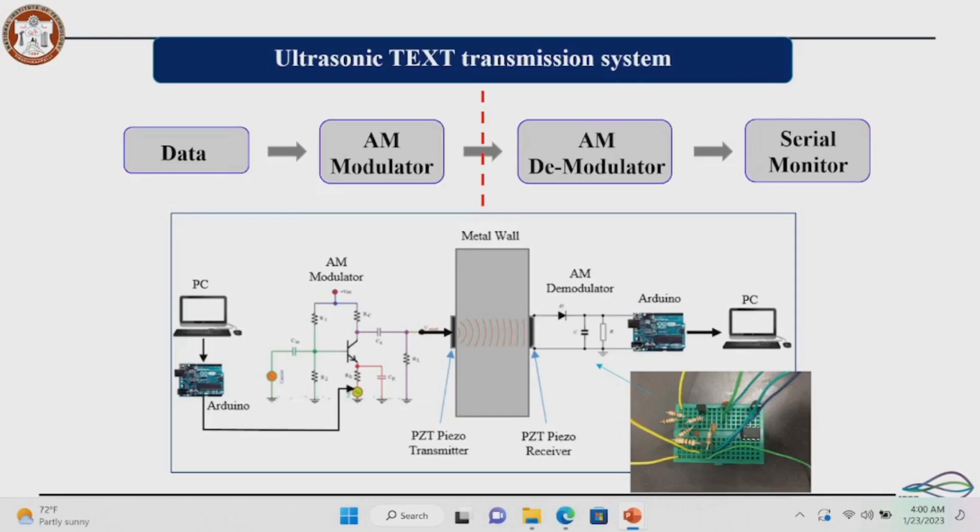How to, if some circuit is there with a proper carrier frequency generator, then we have to alter the piezo according to that. Okay, and also sometimes the paste we are using to stick the piezo on the block, the thickness of the paste, like the glue we are using, also affects this. So there are multiple parameters which need to be addressed during this development.